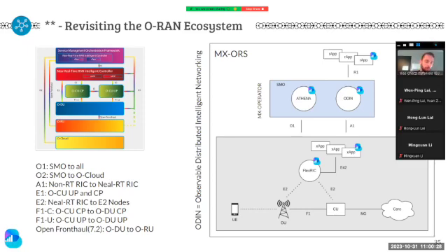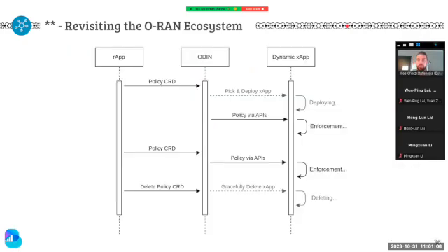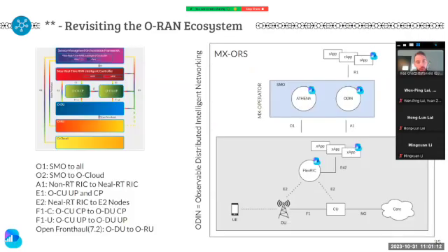So Odin is more for the control part and is more about sending the policies, finding the appropriate xApps to control the RAN. And on top of the SMO and Odin, the non-real-time RIC, we have several rApps that can enforce policies that are intent-based, maybe. They enforce policies, they monitor the network, and they can bring a certain desired behavior. So this is the whole ecosystem, and maybe we can go now to see how a policy will be sent. We will see now the traffic flow, how these policies can be forwarded and sent from the rApps down to the RAN.